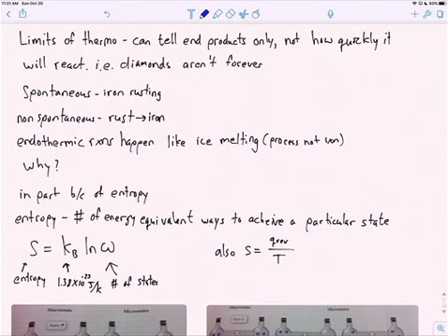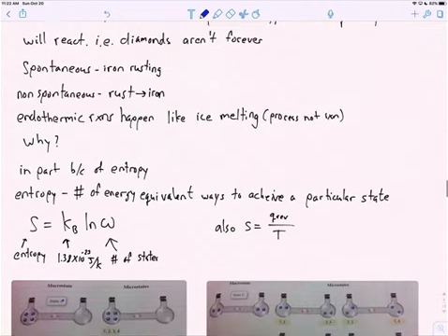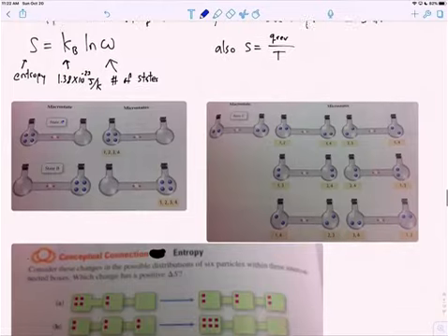And then if entropy is reversible heat transfer over temperature, if there's no heat transfer, there's no change in disorder. So if you want something to not become more ordered, what do you do? You prevent heat transfer. So insulation. If there's insulation, a process will have no change. So the term adiabatic. Adiabatic means no heat transfer. Adiabatic also means isentropic. Iso entropy, same entropy, isentropic. Adiabatic and isentropic are interchangeable in that regard.